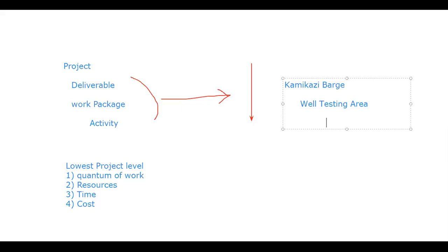And how to describe that activity? Well testing area, and then you have to go to the three-phase separator. And then there might be further three-phase separators. There are multiple three-phase separators. You can go by the tag number to get to the accurate one. And then you have what you need to do on this separator: removal of sight glass.